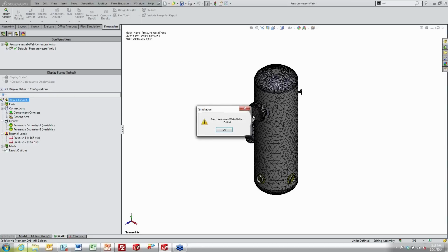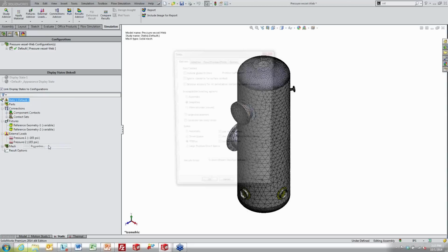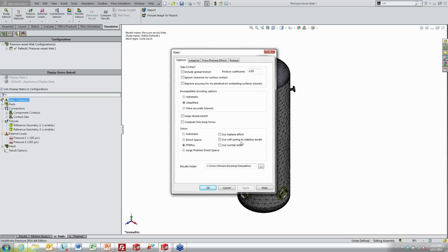So my boundary conditions are two things. One is everything in the fixtures. And the second boundary condition is everything under the connections. Now it's hard for me to tell where the issue is looking at this big assembly. Even bigger assemblies, it would be more difficult. So the way we can find our errors, figure out where they are in this huge assembly, is to turn on this option in our properties called soft springs.